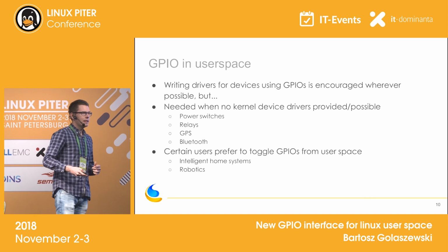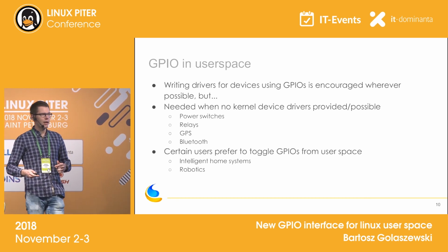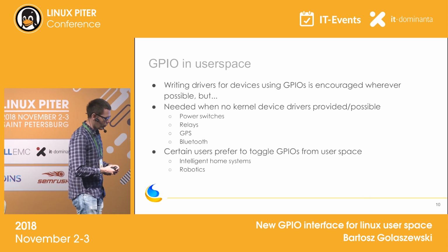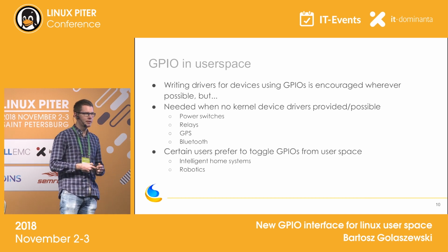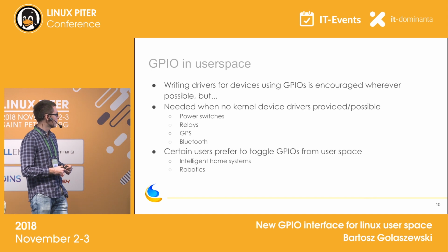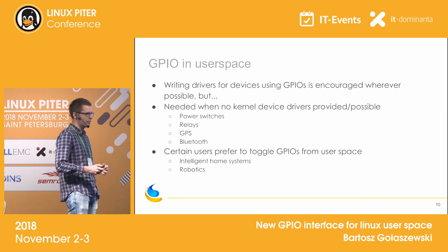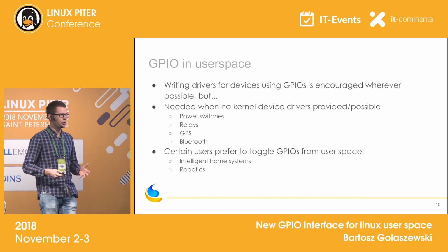In general, the idea is that you should be writing drivers for devices that make use of GPIOs, but this is not always possible, or not always necessary, or sometimes it's simply unwanted. For instance, oftentimes when you use power switches or relays that are controlled by GPIOs, you want to control them from Userspace.